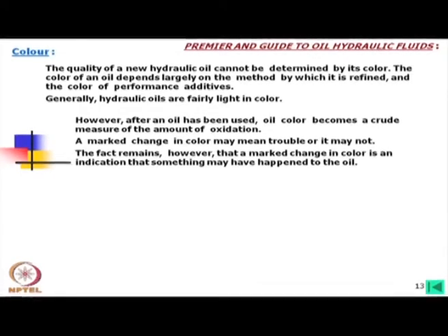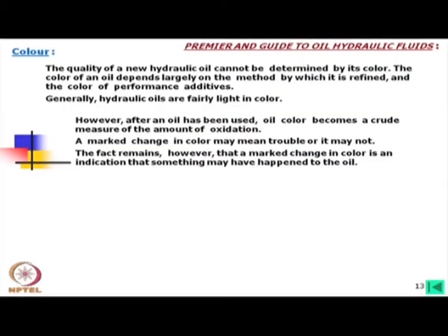Among the hydraulic components, in any hydraulic system, the first thing perhaps is the oil, which has to be changed periodically, and that period is shorter than any other. Next might be the seal, you have to change the seal. So, in that way we have to continuously inspect the oil condition. This is the health of the oil or the specification of the oil, we should check from time to time.